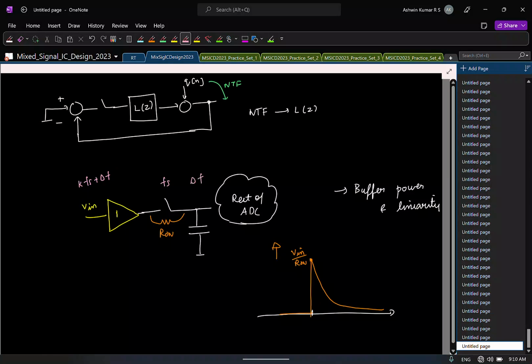This is aliasing. This is something fundamental that is not preventable, right? But what can you do to reduce the effect of aliasing? You have seen it, right? The point is, before sampling, if this signal has content at fs plus delta f, you are gone. So what can you do to reduce the effect?